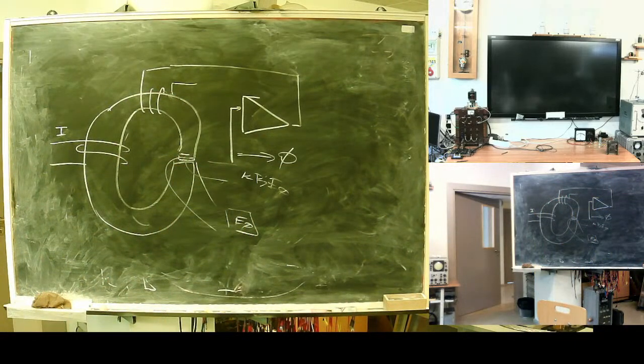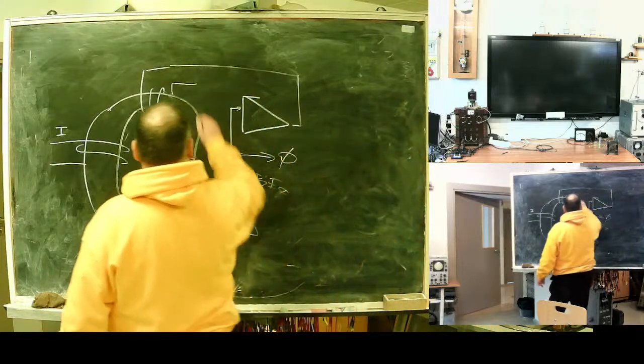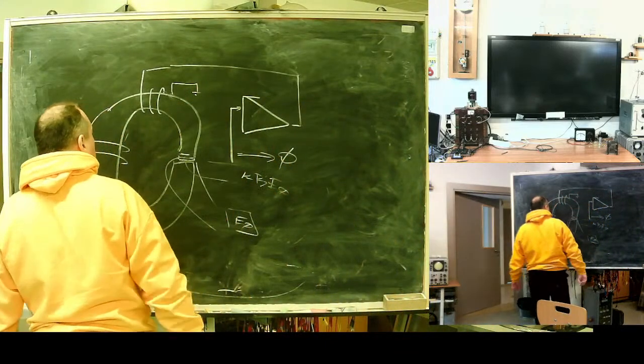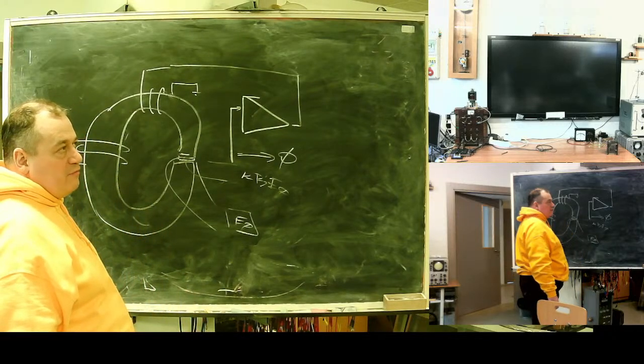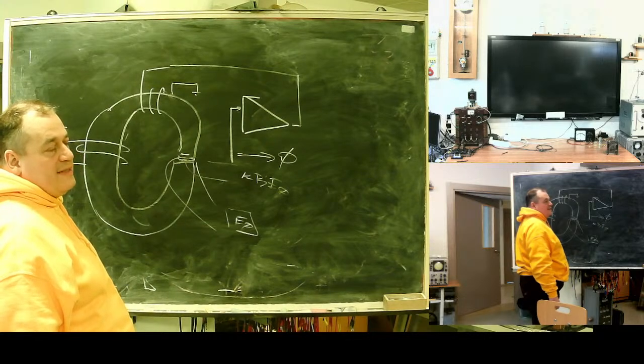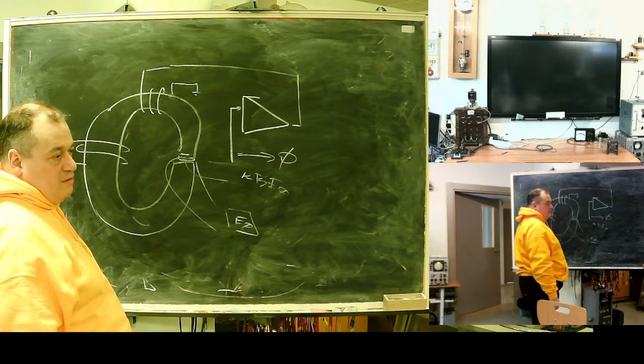Here it is, this IC with 2 transistors is an amplifier, and with the help of the supplementary coil, it tries to make the Hall signal 0. In such a case, it will be as linear as it can be, and will virtually have no zero drift, no zero offset.